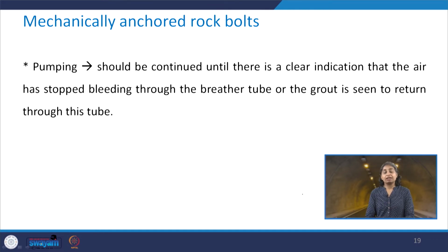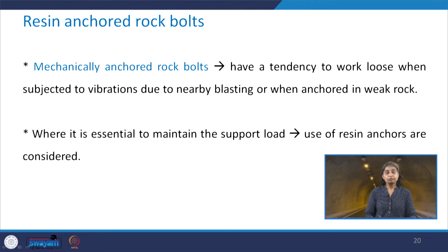So, how long should the pumping be continued? Here is a point regarding that. Pumping should be continued until there is a clear indication that air has stopped bleeding through the breather tube, or if the grout is seen to return through this tube. This will ensure that no more air is there and one can stop pumping the grout.